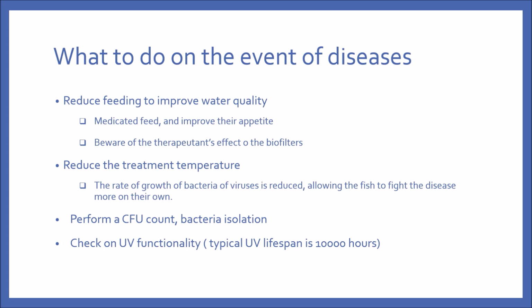For example, usage of antibiotics is not recommended in RAS. Antibiotics will not only kill off the pathogen, but it will also kill off the nitrifying bacteria that is used in the biofilters. Another way is to reduce the treatment temperature. By reducing the temperature, you reduce the growth rate of the bacteria, allowing the fish to fight the disease on its own.